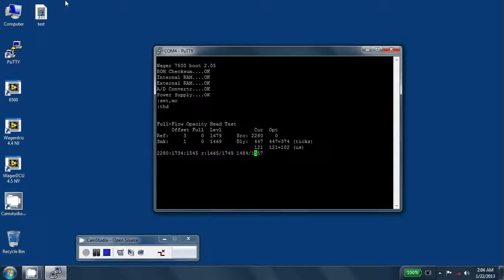You'll need a small flat blade jeweler screwdriver removing the cap on the end of the tube, and looking down in you'll see a circuit board, and on the circuit board will be a potentiometer with a brass flathead screw, and we're going to go clockwise on that screw and bring that 1700 number up to around 2100. And you can see pegged maximum was around 4,000, so if you see 4,000 it will not be jumping, but let's go ahead and around 2100.